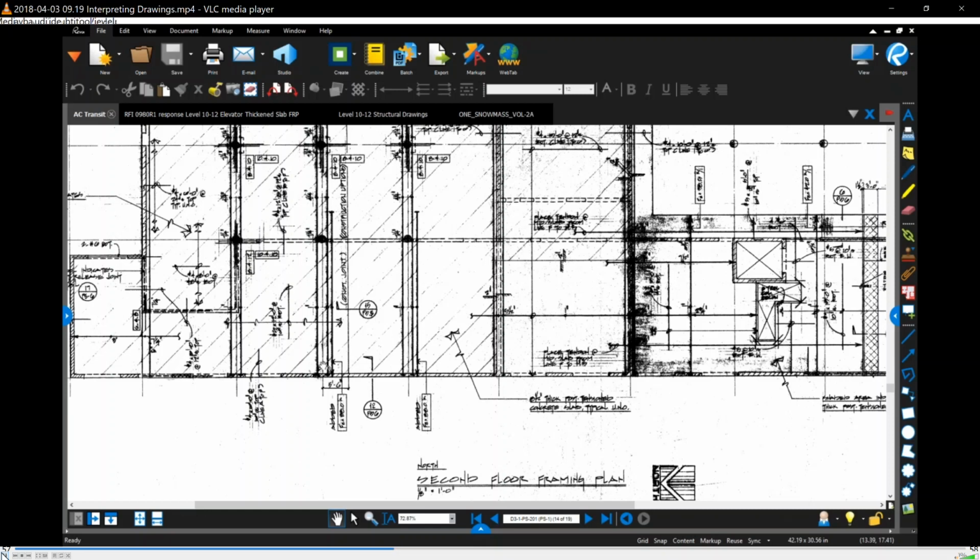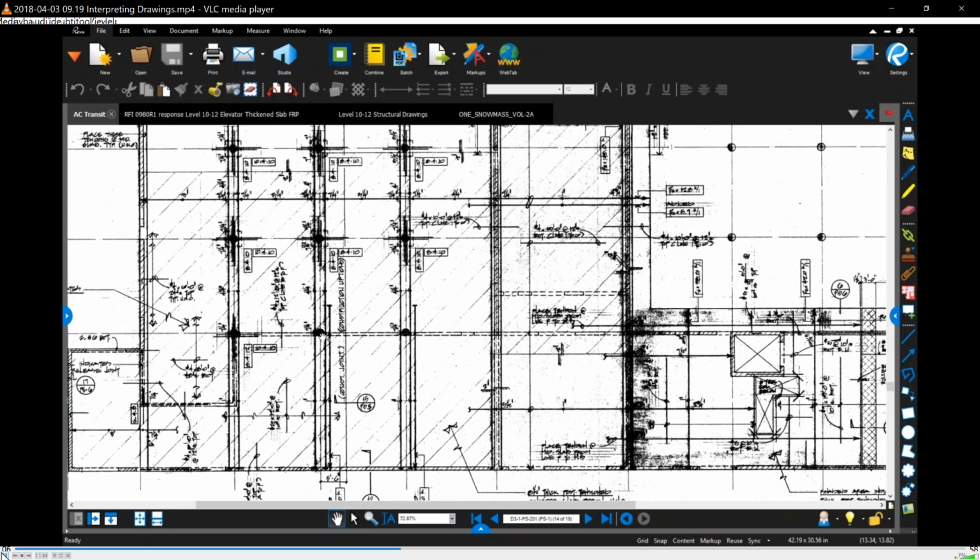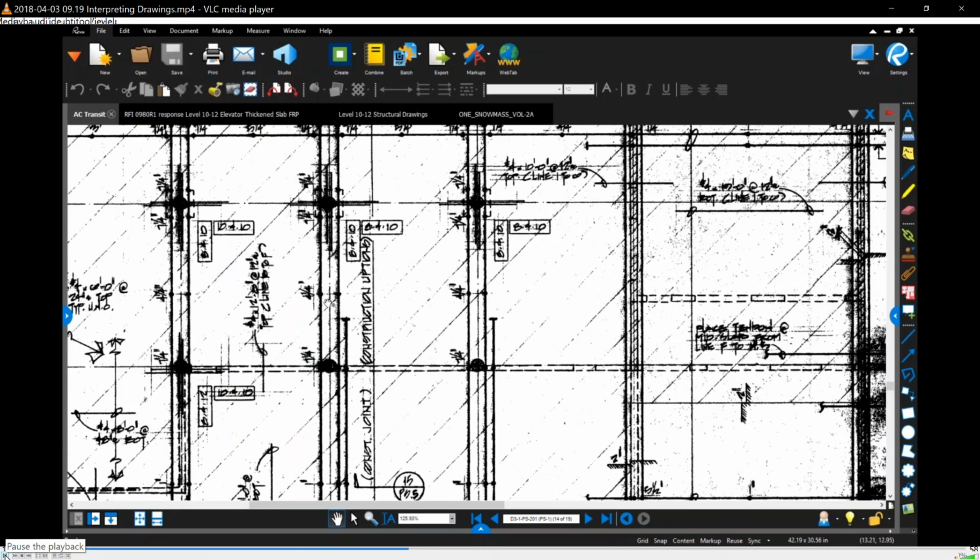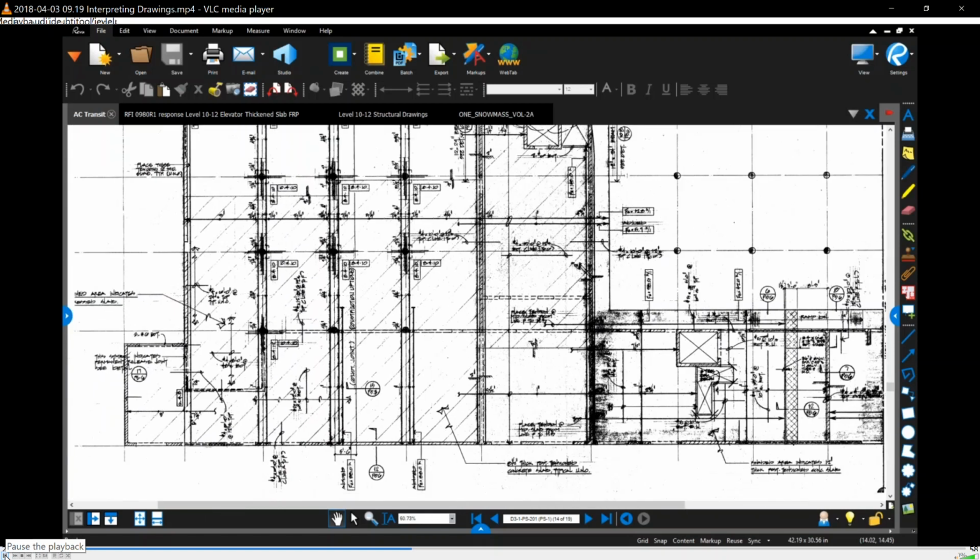And you're not getting the full profile, right? Your tendon profile is half at mid-height of slab here and at the top point here. Whereas this particular span is shorter, you're getting a high point tendon here and a high point tendon here, and you can basically do this all the way to the lowest point if you want. You can see it's only at 4 1/4, so it didn't need to get as much uplift there.